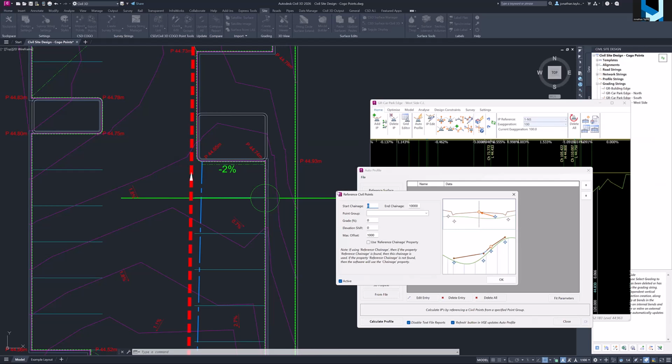That doesn't mean that we can go in and edit, for example, an elevation here, if this is going to wipe it out and say, don't care what the design is, just use Cogo points. So I know that this area is from chainage about 42 to chainage 52. Look for any Cogo points, and this is where we'll look at the point group in a minute, that have a description called SO. Conveniently ours do.